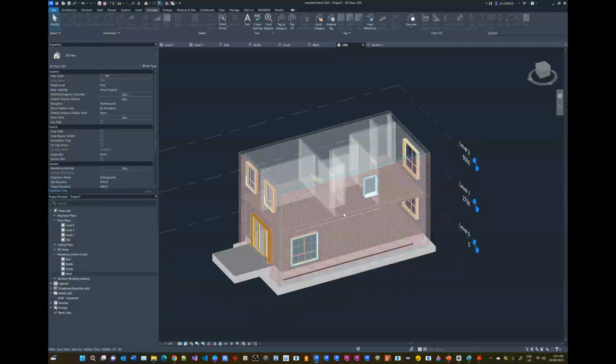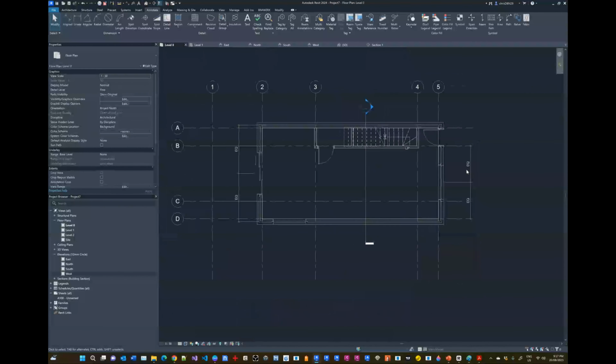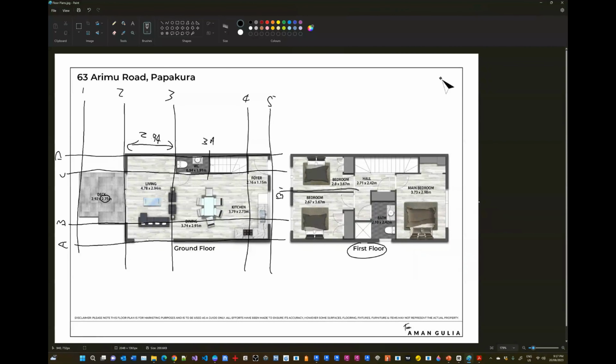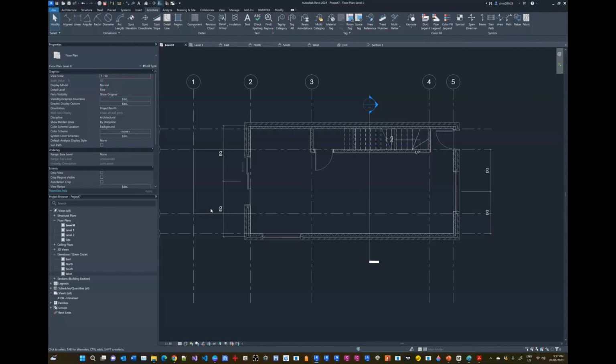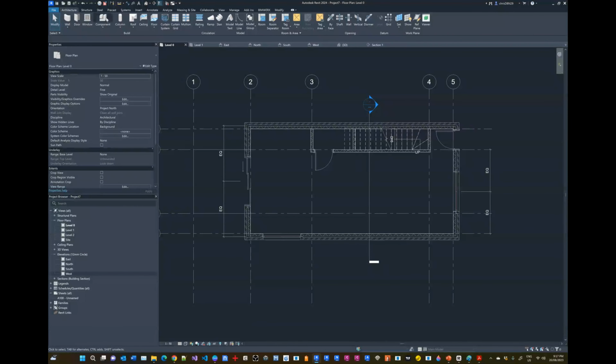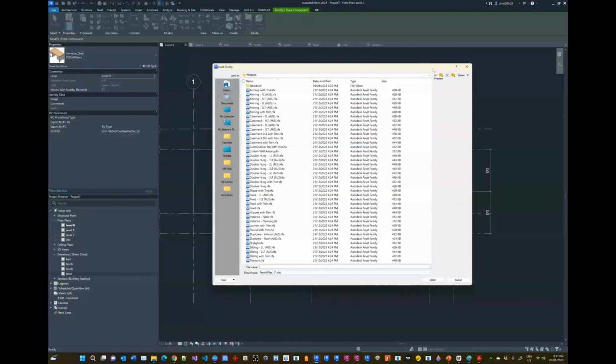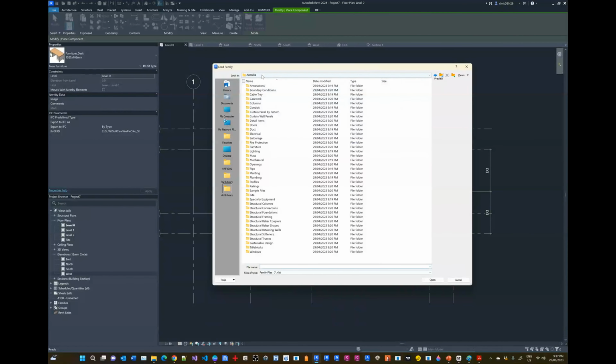Now I'm going to show you how to place furniture in the model, and then it's going to be your turn to start placing all of the furniture in the model as you see them there. I'm going to place one toilet and maybe the dining room table for you, and then you can do the rest. So let's start with that. From the architecture ribbon, I'm going to click on the component button, and then I'm going to load a family. So in our categories, I'm still on the Australian one. We can switch back to the New Zealand library. It doesn't really matter. But what I'm looking for is the plumbing fixtures.